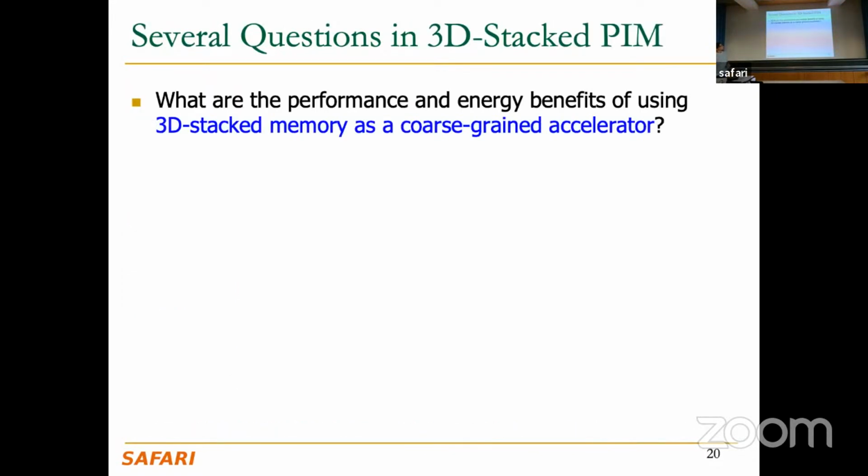So when it comes to creating processing-in-memory systems with these types of memories, for now we focus on 3D stack memories, but most of the things that we are going to discuss for 3D stack memories are applicable to 2D memories as well, to things like the NDP architecture, for example, that is 2D memory, right? It's implemented on DDR4 chips. But let's start with the 3D stack memories because they have very clear advantages.